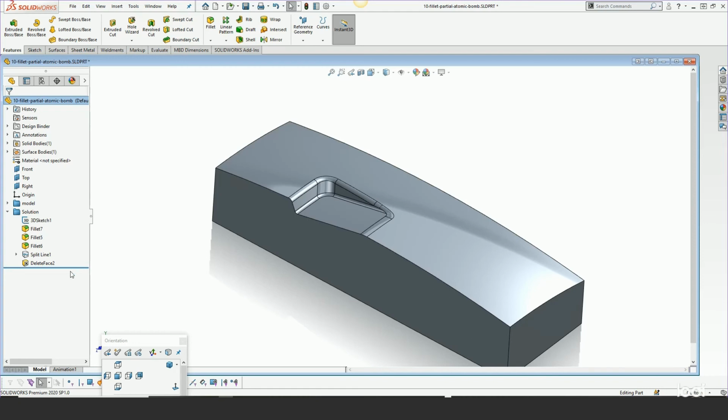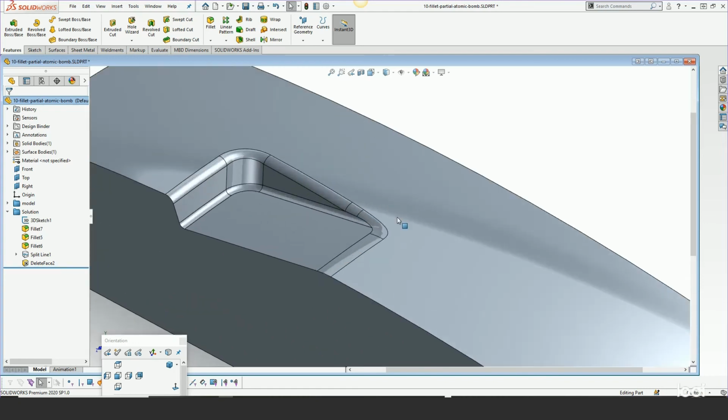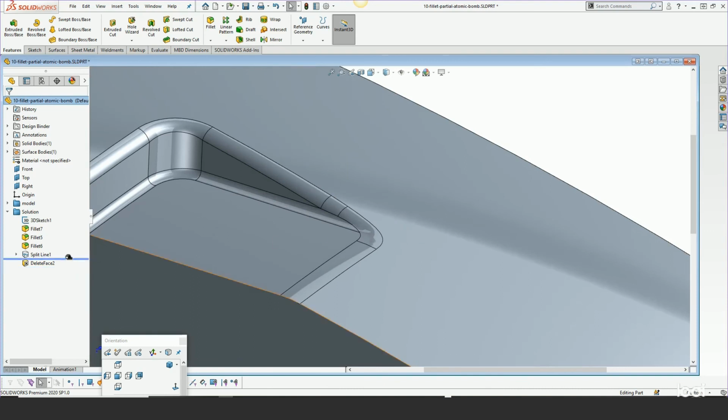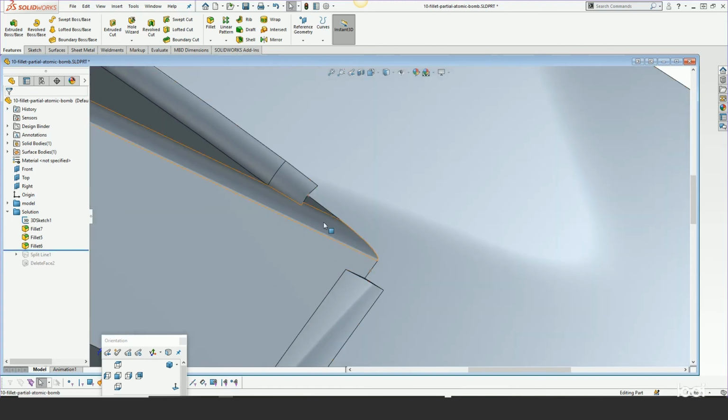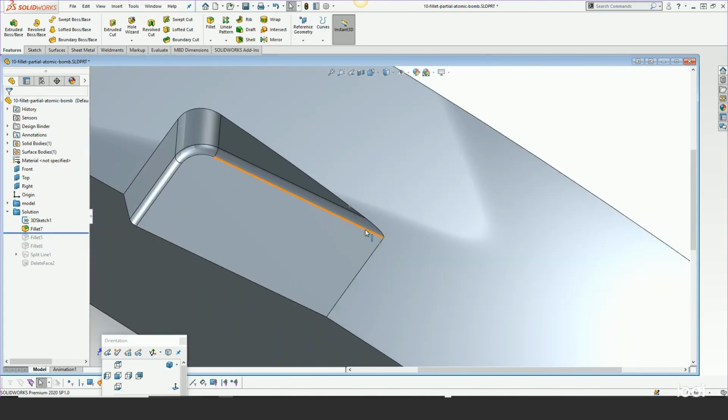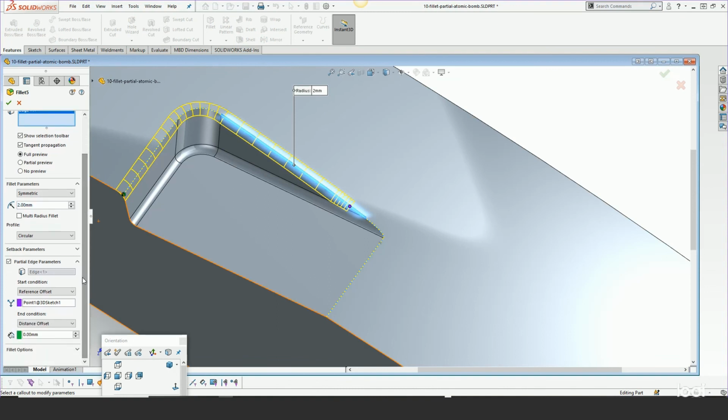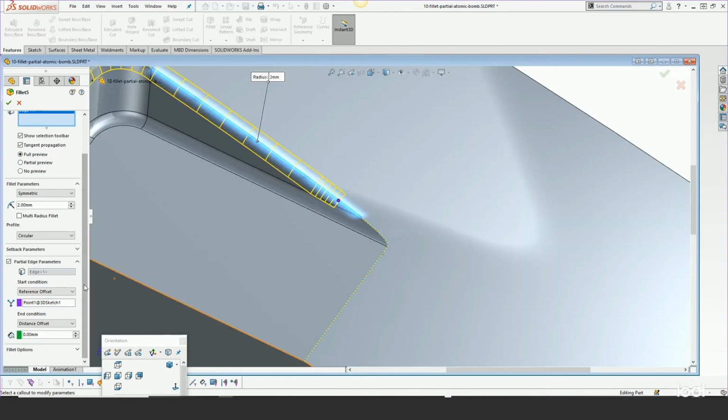So I guess what I'm getting at is a slightly different method. It's still the idea that you would isolate the corner from the fillet, not understanding how to do the transition. So here I can do my face-to-face with chordal width at the bottom, but the difference is that when I start to apply these fillets, I'm using the new feature in 2019 called partial edge parameters. And here you can use it with a reference point.